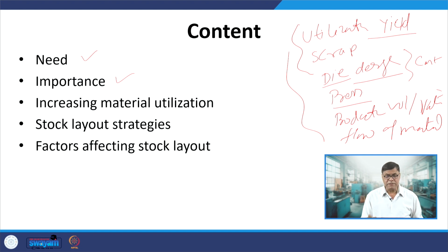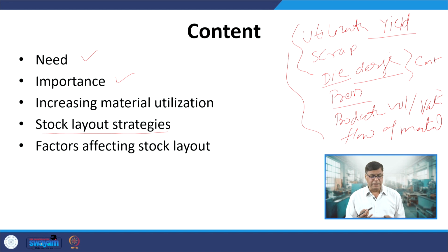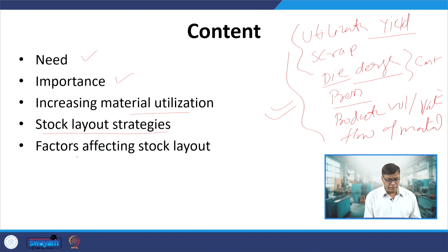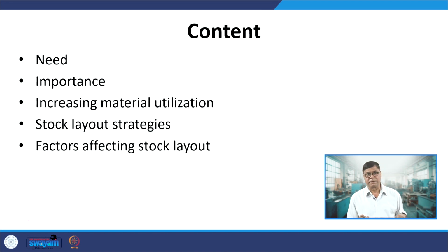So, in this presentation we will see the different strategies related with the stock layout, primarily to increase the material utilization, reduce the scrap and achieve all these benefits, so that the product can be made at low cost with greater material efficiency. The various factors that affect a stock layout will all be covered in this presentation.